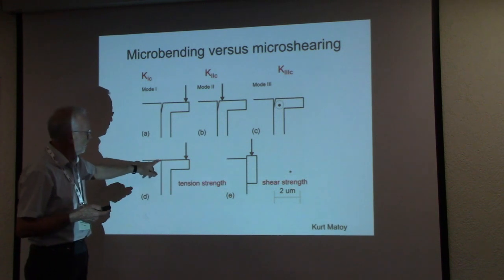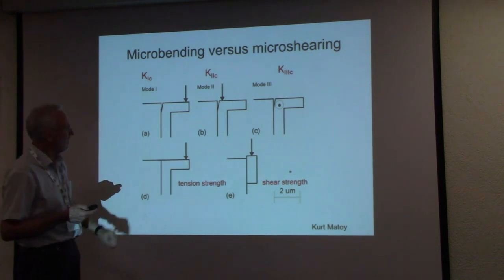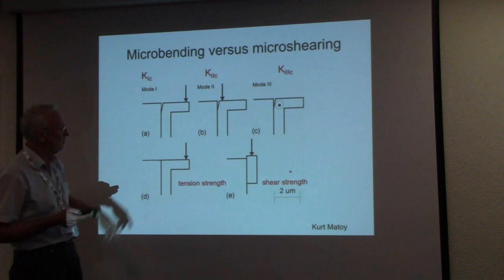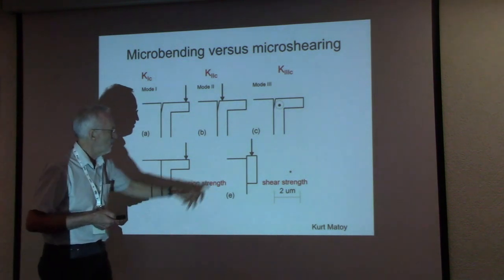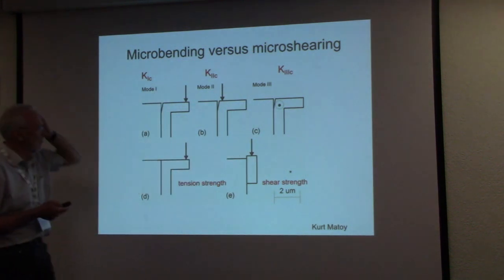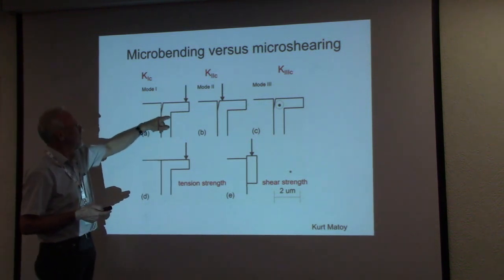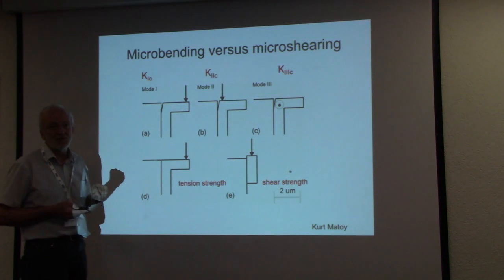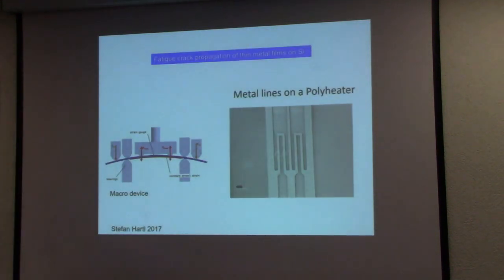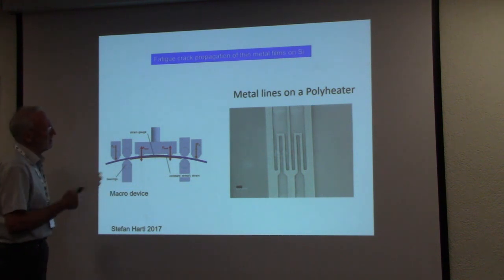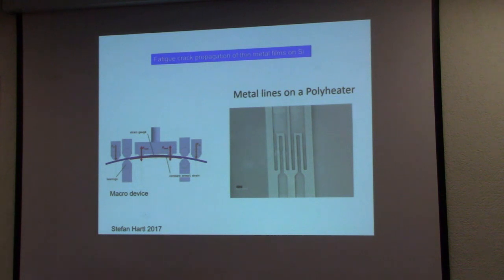But it is important that no plasticity should take place, otherwise it will again be size dependent. Or here the shear strength can be determined. And when the cracks then generate, then you can measure the toughness, even for these materials. But you have to take into account the difference in the elastic properties and the multiaxiality of the loading, or the mixed mode loading of the crack.